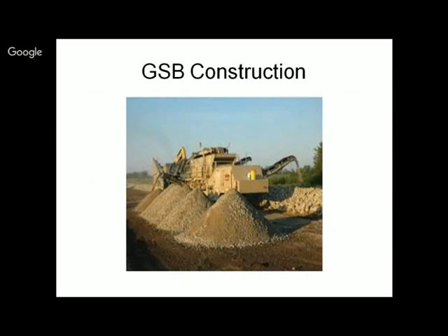that whether the CBR value is as per requirements. अब इसके बाद एक चीज होती है जिसको हम बोलते हैं डिजाइन। जीएसबी का डिजाइन, ग्रेनुलर सब बेस का डिजाइन लेबोरेटरी में क्या करना है, जो भी आपका ग्रेडिंग मटेरियल आया है उसके ऊपर हमने ओएमसी एंड एमडीडी निकालनी है। We just need to know कि कितने इसमें मॉइस्चर चाहिए होगी और कितनी इसकी डेंसिटी आती है, because that is the tool which is to be used for the quality control at the site. So density is the only most prominent quality control tool which is to be used for GSB.